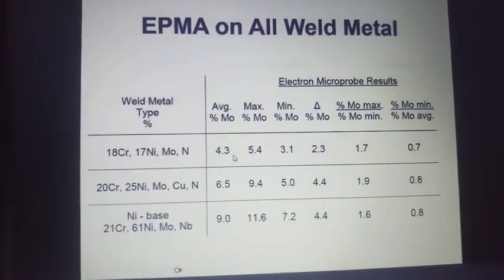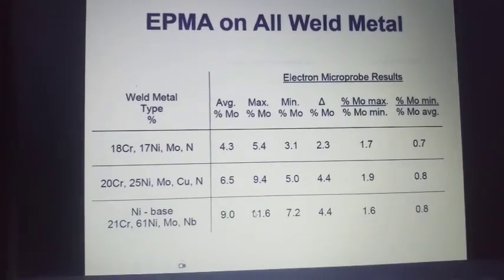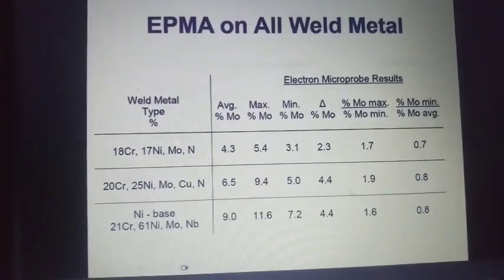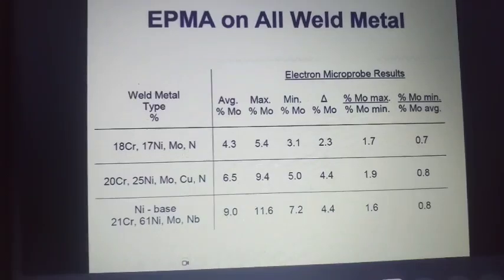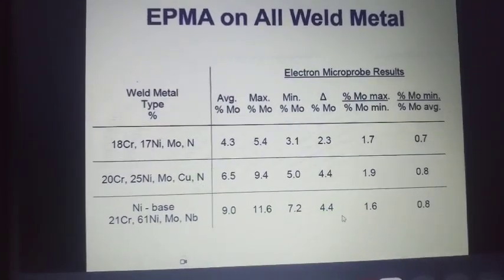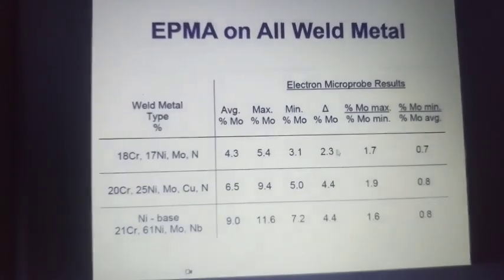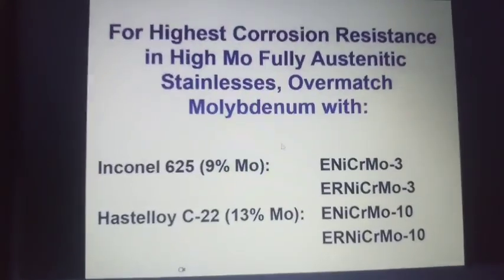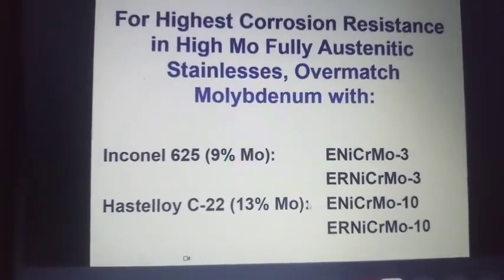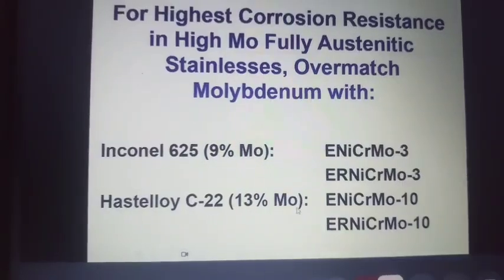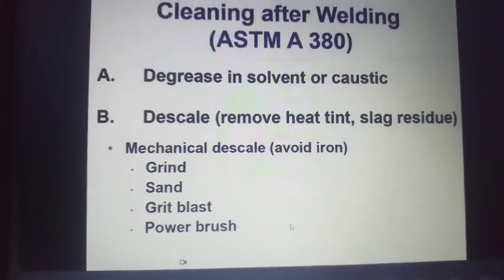Ramakrishna sir, when you come across this problem, just check the moly. When they report only weld is pitting, base material is not pitting, just check this and you will find this problem. In such cases, we need to overmatch the filler wire a bit, put more moly in the weld to have a superior corrosion resistance.